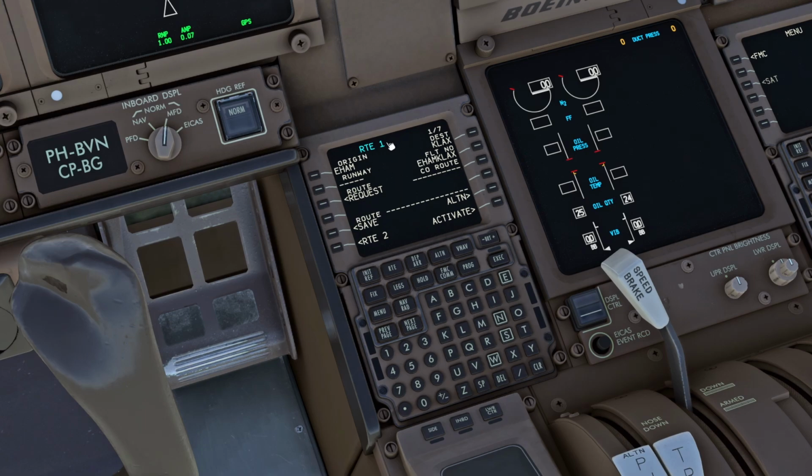I did find that it does not always do it completely correctly, but we're going to enter a runway and then also enter our flight number right here, or call sign. This is what ATIS also sees. Runway 24 is active today, so I'm already entering it. So I'm going to activate that and execute.